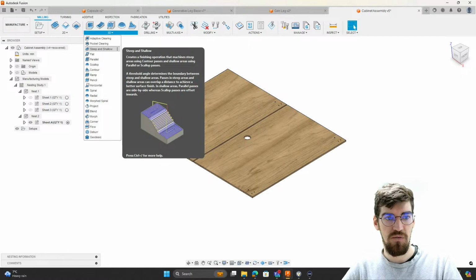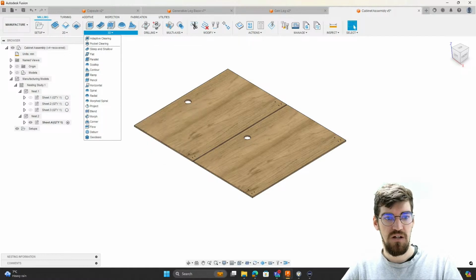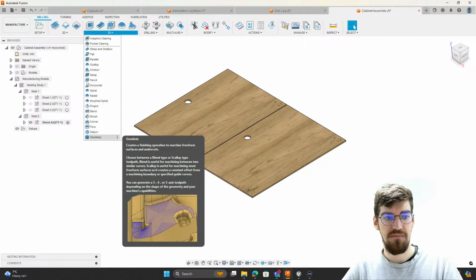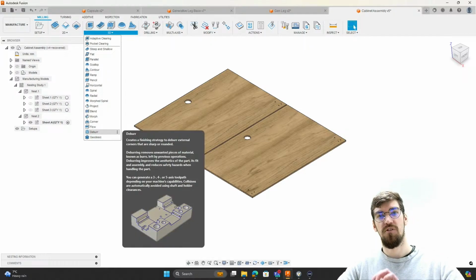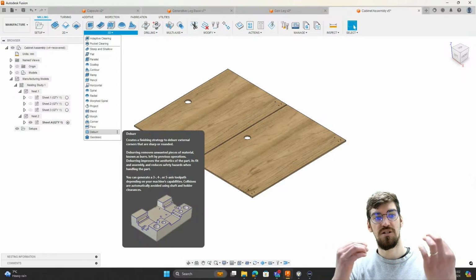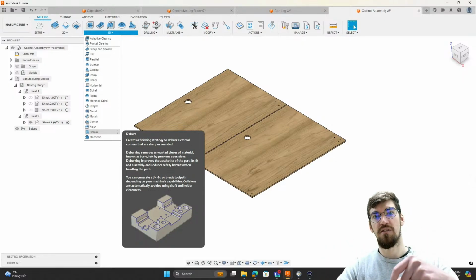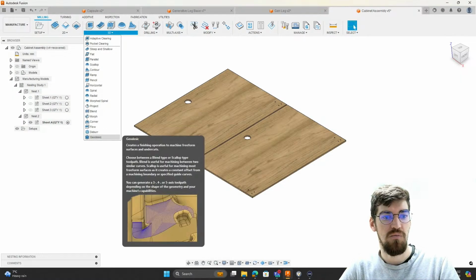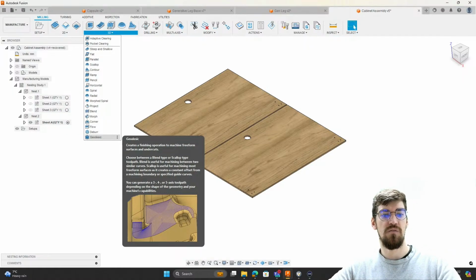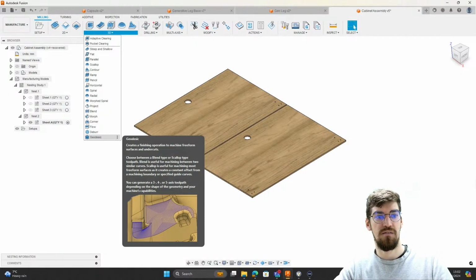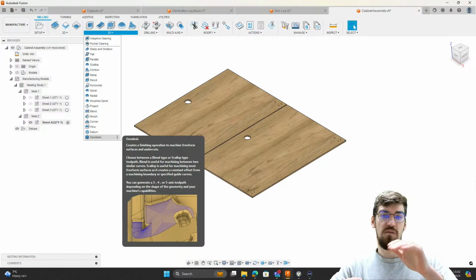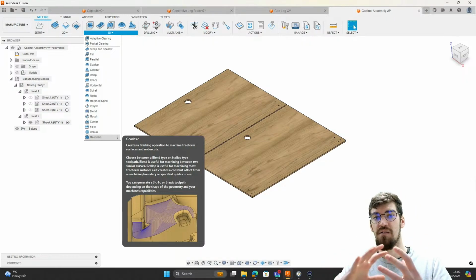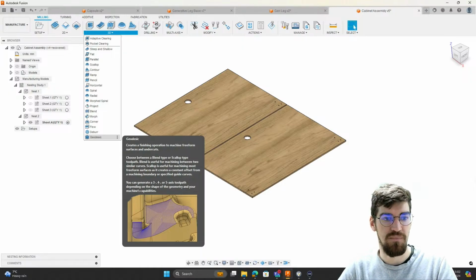So we've got steep and shallow that's available within the extension. We have deburring and geodesic. So deburring is just going to go along any of the sharp corners, sharp edges, and then neatly neaten those off with a chamfer tool or something, just to make sure that we don't have any burrs left behind. Geodesic is going to trace along surfaces a lot better than some of the other strategies will, actually tracing nice and neatly against the surface that we decide, rather than having to try and limit the area in which we're machining along the way.